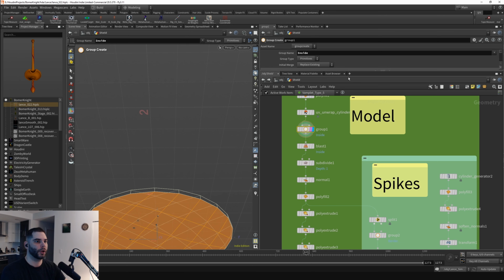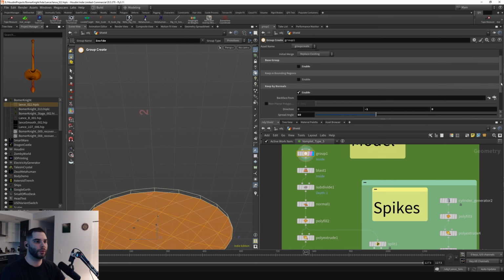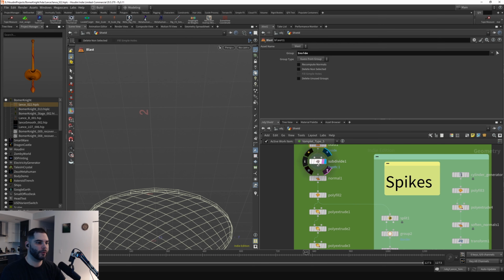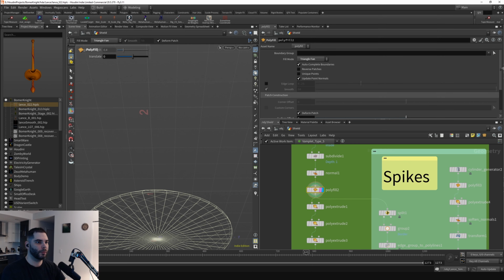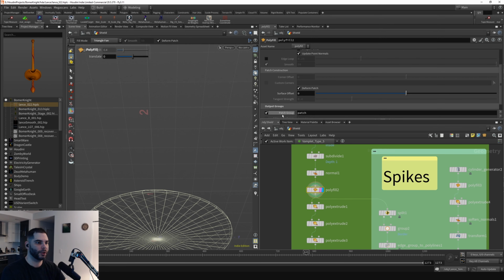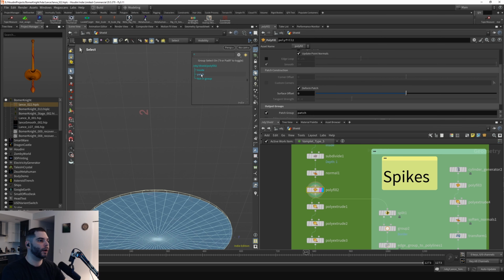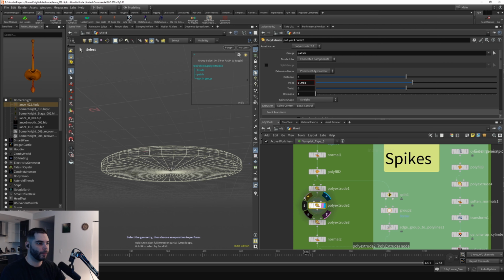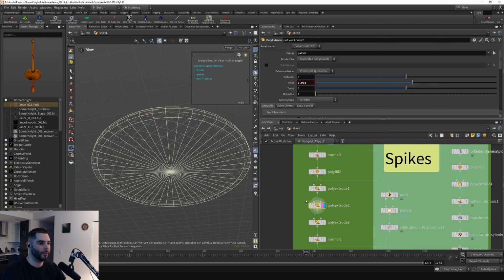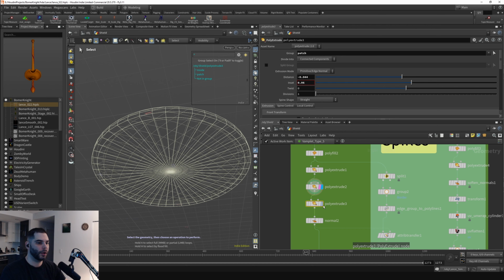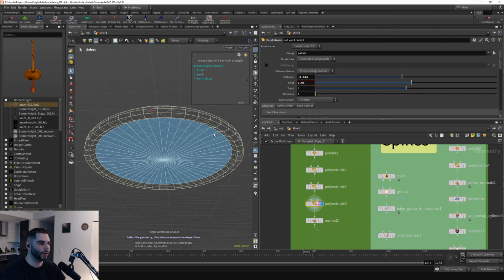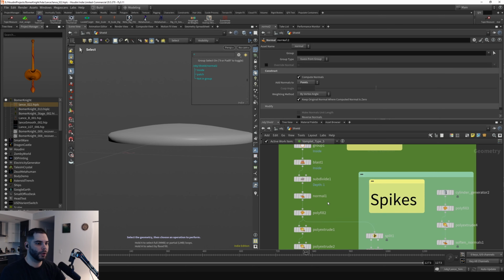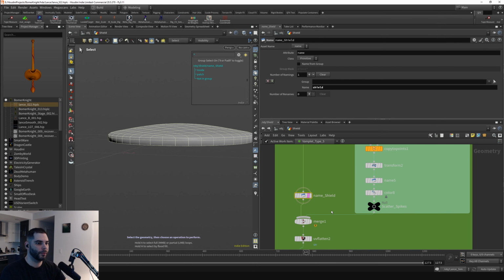Okay, no, I grabbed the bottom surface with this normal, and then removed it, subdivided everything, polyfilled the bottom, made sure I put the patch group, and then now we have that patch on the bottom. Then I extruded that patch out, and then did an inset on the bottom and extruded it in. I guess it's like the back side of it.